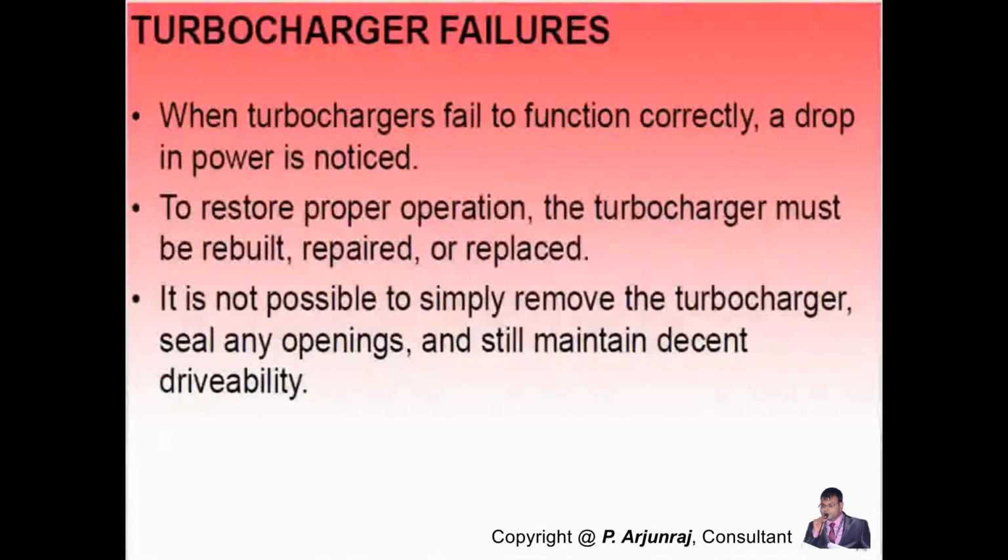Okay, is this manually adjustable? Yeah. So your question is about it being adjustable. Basically, it is an electronically controlled wastegate. Depending upon the boost pressure, the value you get from the exhaust gas is sensed accordingly, and it is programmed with the help of the control unit system.